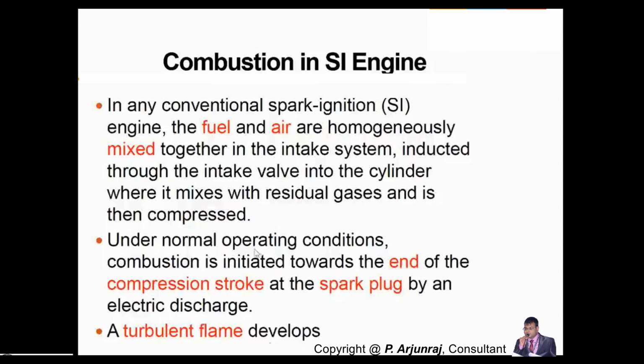Under normal operating conditions, the combustion is going to initiate towards the end of the compression stroke, when the piston moves from BDC to TDC, nearing the completion of the compression stroke. At that time, the combustion gets initiated when the spark comes into action by discharging the electric current. Once the combustion starts, you are going to get a flame, nothing but a turbulent flame. You are going to get turbulence out of it.